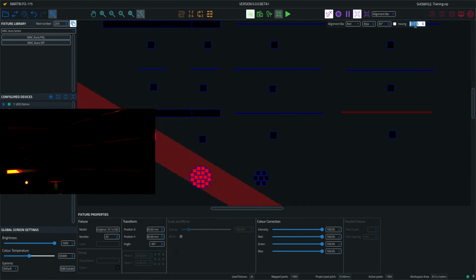It will automatically output the light from that fixture right away. So you don't need to run back and forth to the lighting console. Test pattern with DMX override enabled will just output video or test patterns from the fixtures regardless of where they are right now with their DMX. So really useful tool to have as well.